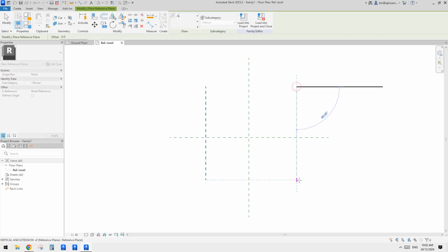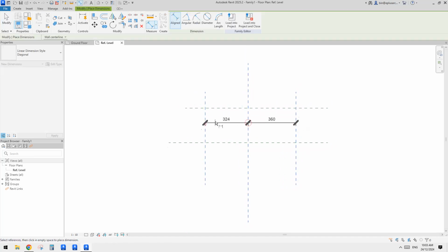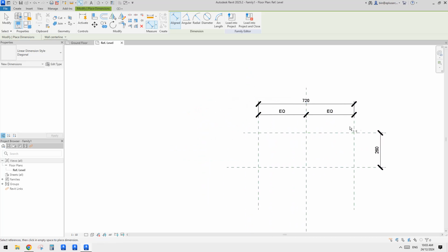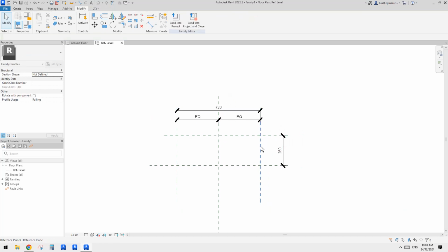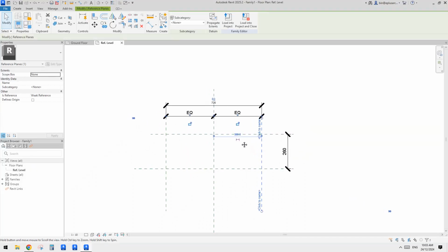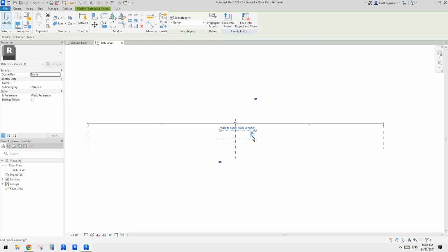First, we're not going to make this fully parametric, but just roughly to give us some reference. I'm going to add some dimensions so we know how big it needs to be, right? 7 to 20 is probably not enough. From the image, this is a model, but we probably want to use real world dimensions. How about we make it 9 meters wide, so 4,500, and maybe 3 meters high.